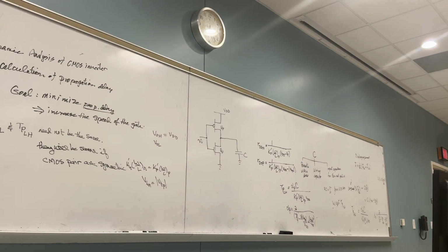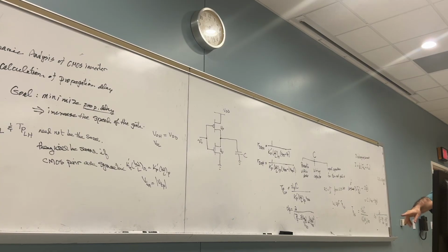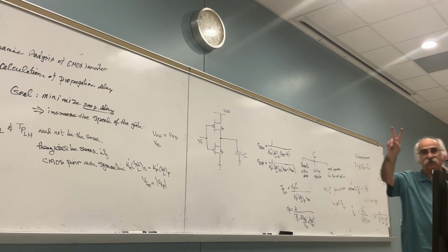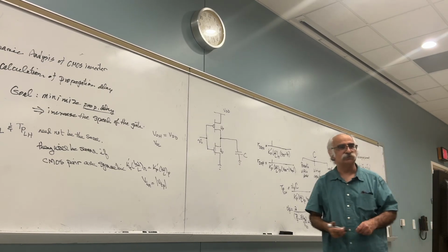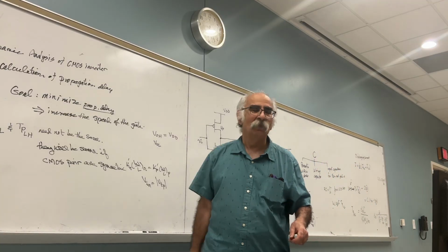Which means if you have, for example, a 3-input NAND gate, design first a 2-input NAND gate, and combine its output with the third input, such that the overall is equivalent to a 3-input NAND gate. But in this case, you used 2-input NAND gates. Did you get it or not? Remember, for every input you are going to add 2 transistors. I will show you that in just a second.